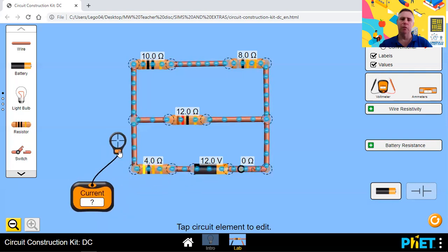Now notice, of course, on the side branch, it's also 1.07 amps, but then it meets a junction. If you look carefully, you'll see the electrons are flowing faster in the main circuit than they are in the branches. So let's check. Through the 12 ohm resistor, the current is only 0.64 amps. And through the top branch, the current is only 0.43. But of course, if you add those two together, 0.64 and 0.43, you get the 1.07 amperes.